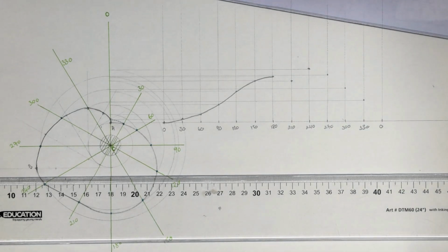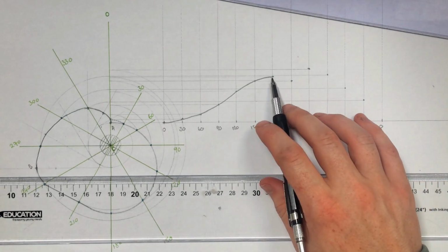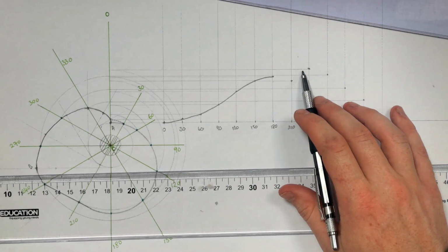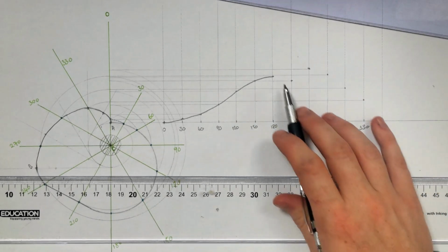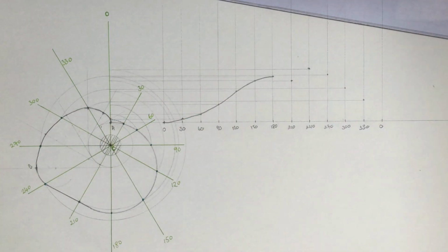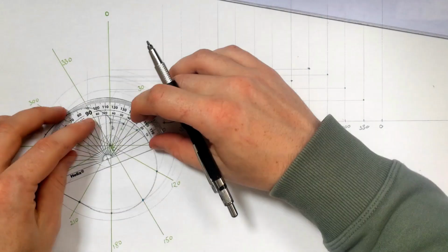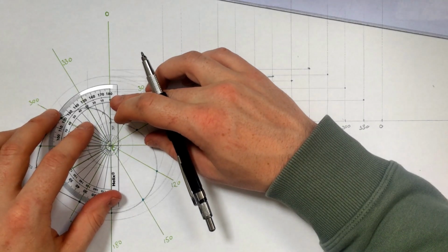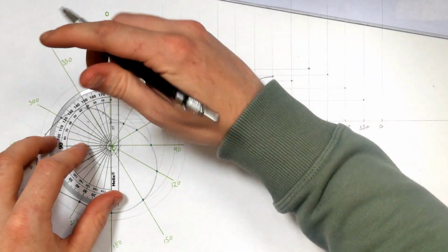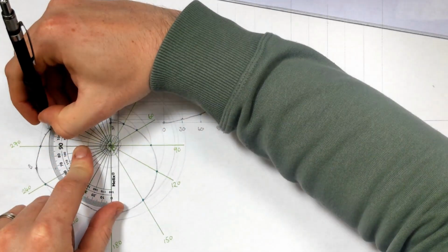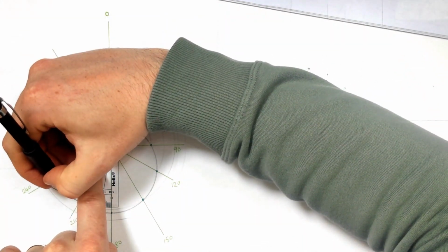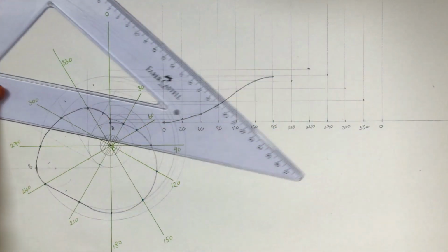Okay, now in here, I don't know if this should be a straight line or should they be curved. So it's a bit vague. Okay, so in this kind of a case, I'm going to add a couple of extra points into my displacement. So we've got 30-degree sections here, but I'm going to add a 15-degree section in between each one as well, just for the sake of getting a couple of extra points on my displacement. I think it'll just help it be a bit more accurate.